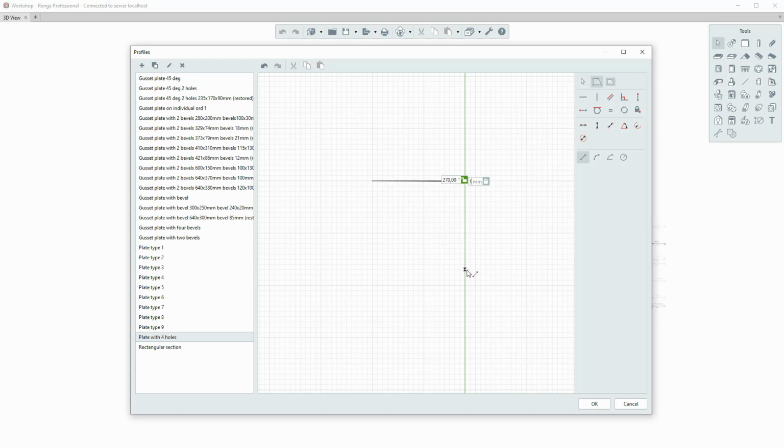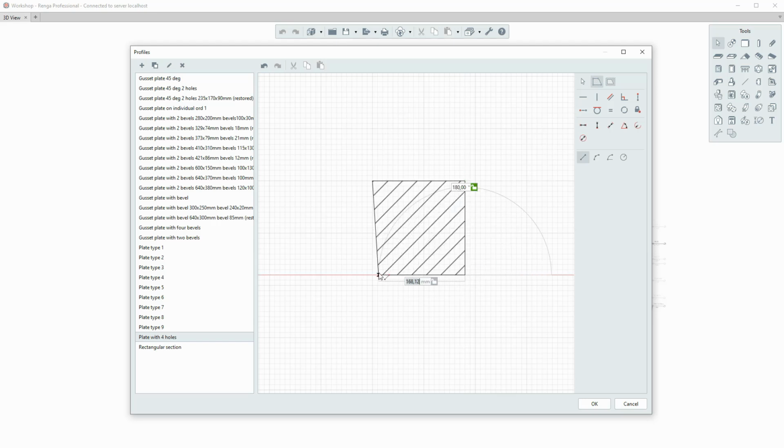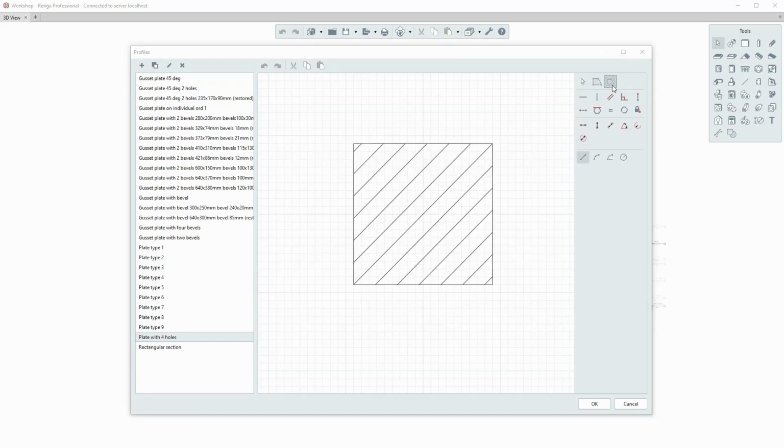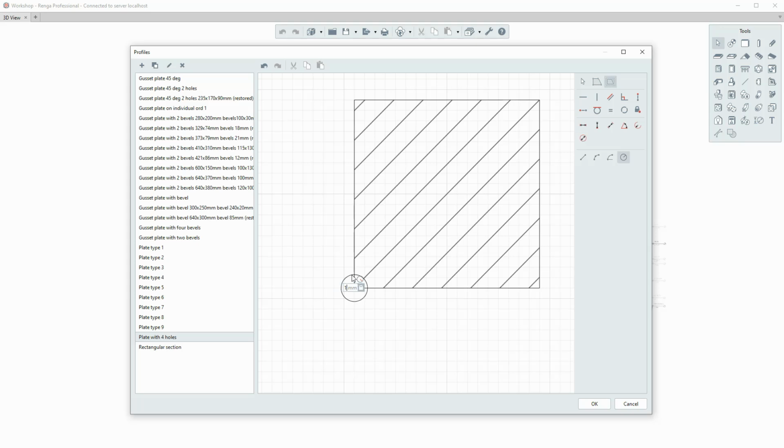The outline or hole is completed by pressing the Enter key. Mind that the outline or hole cannot be created correctly if its borders are crisscross. In Renga, one profile can consist of several outlines and contain several holes. If a solid body will be created from the profile, create it with a single contour. All snaps and accurate construction are available for profile construction. You can edit outlines and holes by handles.